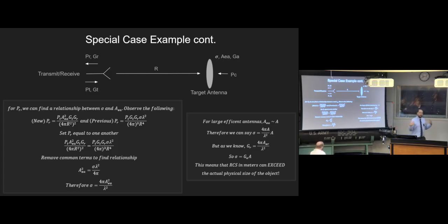For example, think back to that thing I mentioned earlier. Let's say 300 megahertz, same example, replace the antenna with an incident plate, 1 meter by 1 meter, 1 square meter plate. I shoot my 300 megahertz out. I didn't put it on here, but the math works out to say that you would think the RCS at its peak is 1 square meter. It is not. The RCS of a 1 square meter plate at 300 megahertz is 12.5 meters squared.